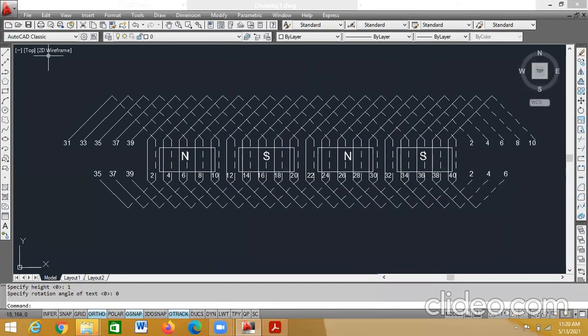Now go for the polyline, third option, draw line, construction line, polyline. Select the polyline option, click here, specify the next point, select half width, H, enter, 0.3, enter, ending width 0, enter. Drag it, you'll get the arrow. Now take the line, draw a line from here.